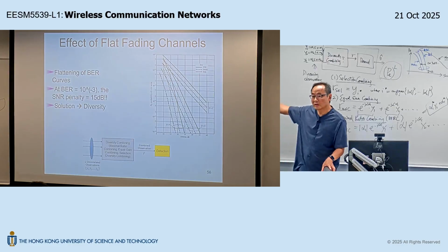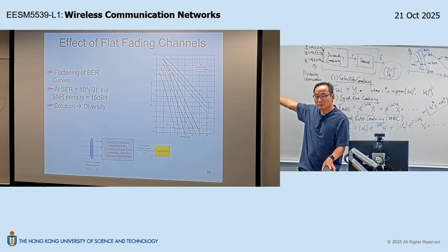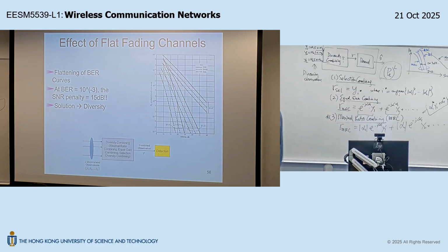So with 4 receive antennas and 1 RF and ADC chain, how should we design the control path? I need to estimate alpha 1 hat, alpha 2 hat, alpha 3 hat, alpha 4 hat, right, in this case. So how should I do this? Using similar logic, I need to partition the preamble into 4 pieces, and each piece will have a switch configuration to estimate the alpha i hat, right? So what's wrong with that?